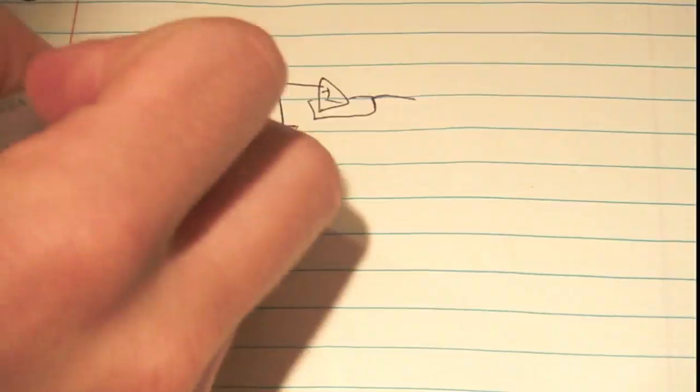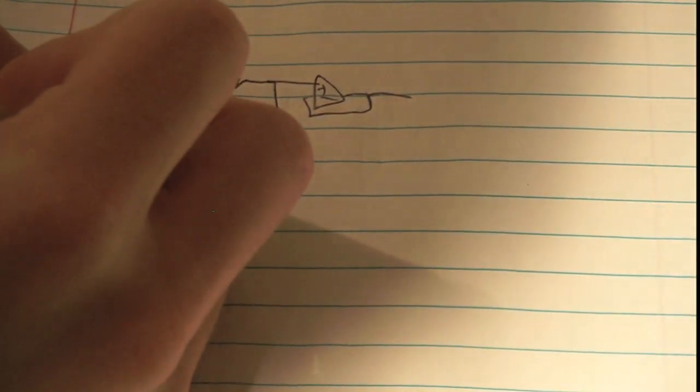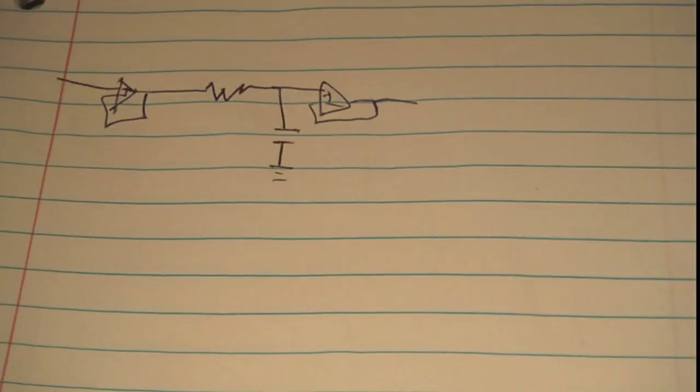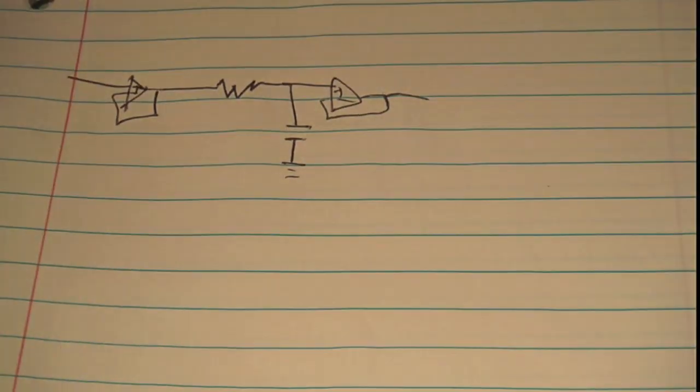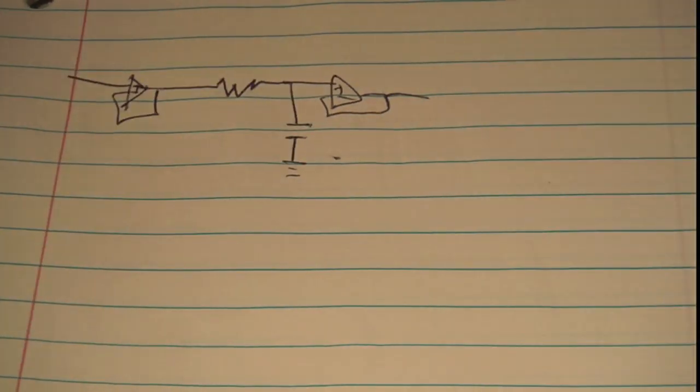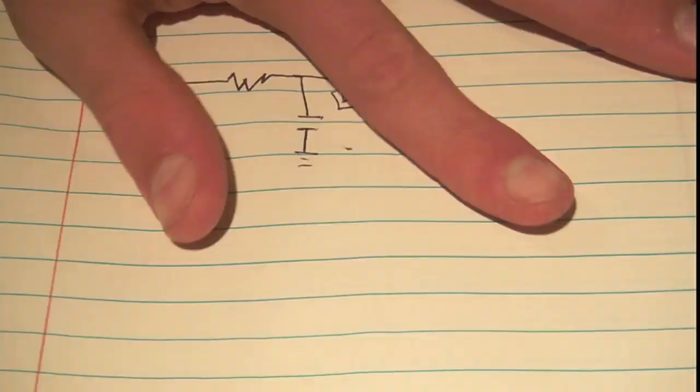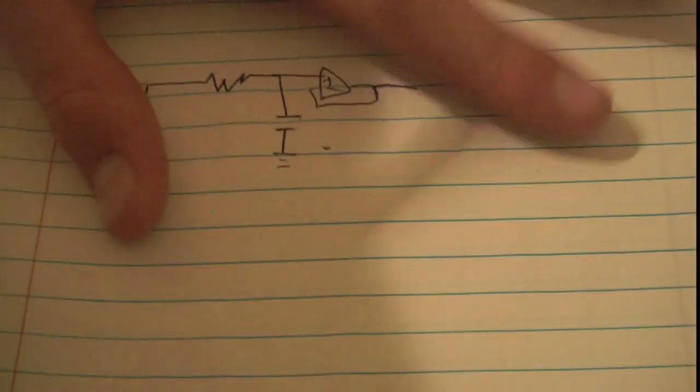So now how do we calculate this low-pass filter? So we have a low-pass filter, right? We know this. It consists of a resistor, a capacitor to ground, and an op-amp at either side to buffer our signal so that we don't get any load from the input or the output influencing our filter. Okay, so this is our basic design here. Obviously, you could go with just this, but then loads on your output are going to influence your filter.